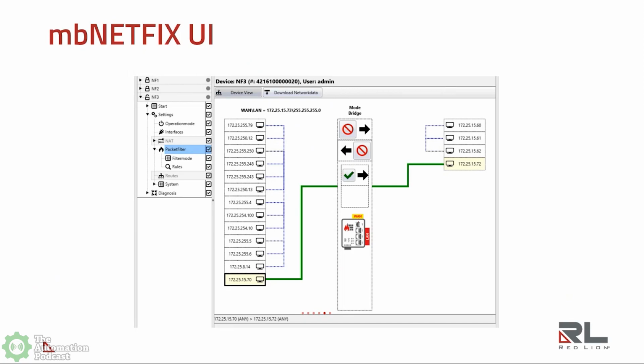And so if you are referring to radios, a couple things about radio technology. It's not full duplex communication, so it's a half duplex connection. And so you really don't want to send a whole lot of information across that expecting real-time response. And then sometimes, depending on what type of radio you're using, if you're using a 900 megahertz radio, for example, that's a very low bandwidth.